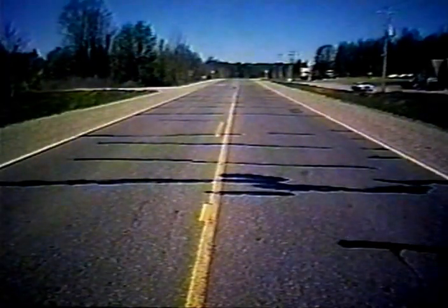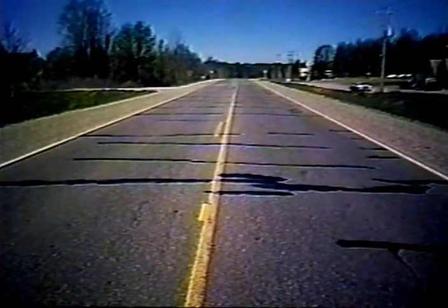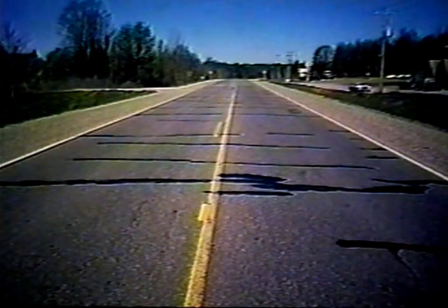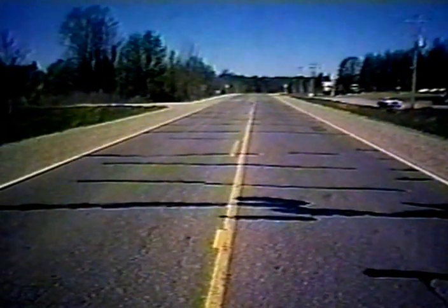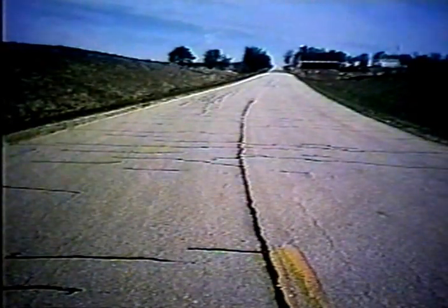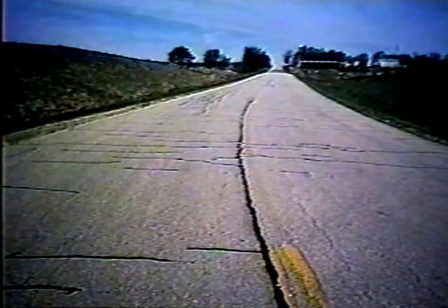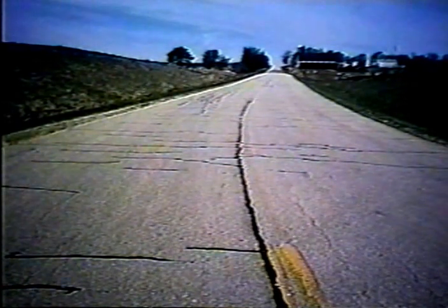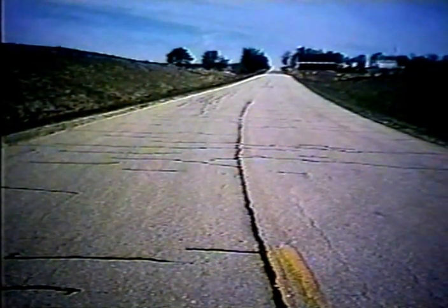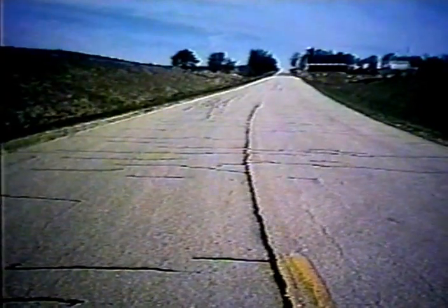But as these pavements begin to age, you see the transverse cracks becoming closer together. It's a way to gauge really where you are in the life of the pavement, the spacing of the transverse cracking. Because as the pavement becomes older, the asphalt becomes more brittle, and really can't expand and contract as well as it did when it was brand new. So you see additional cracking occurring throughout the life of the pavement. This transverse cracking pattern can continue on down to where the cracks are really only a foot or less apart. Another indication that the pavement has aged and is much further along in the life.